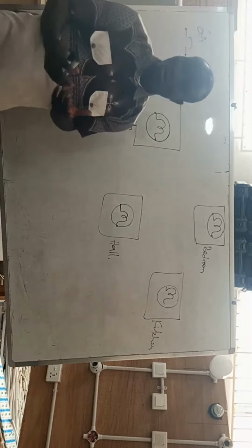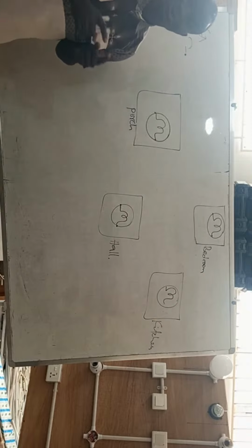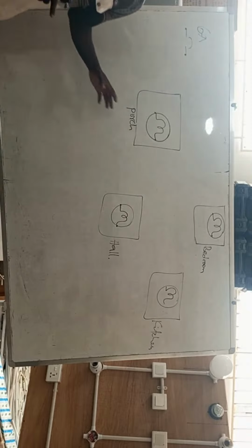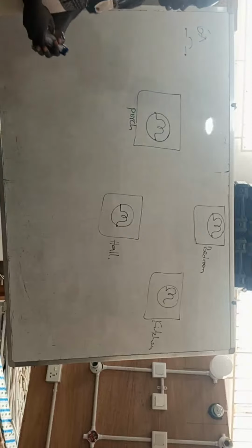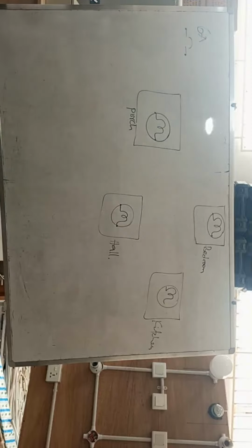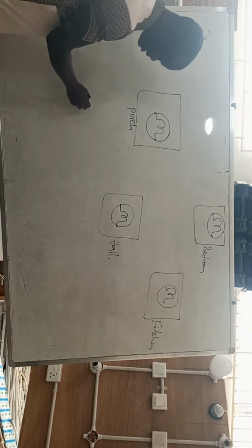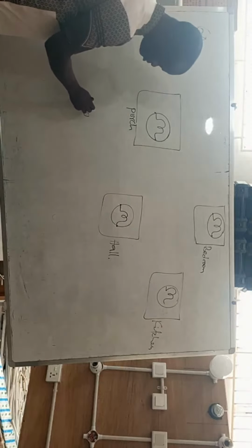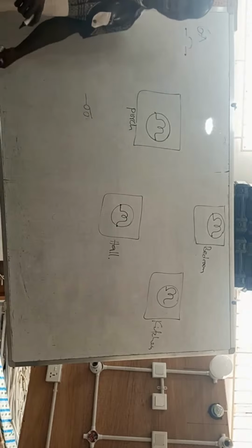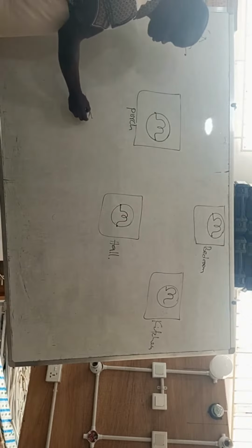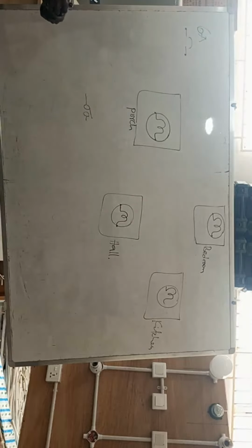Okay. If we are going to control these lamps separately, like I said, then that will inform us to select the correct switch that we can use for that arrangement. So if you are going to do them separately, we can simply use a single pole switch or a one-gang, one-way switch to do that wiring.